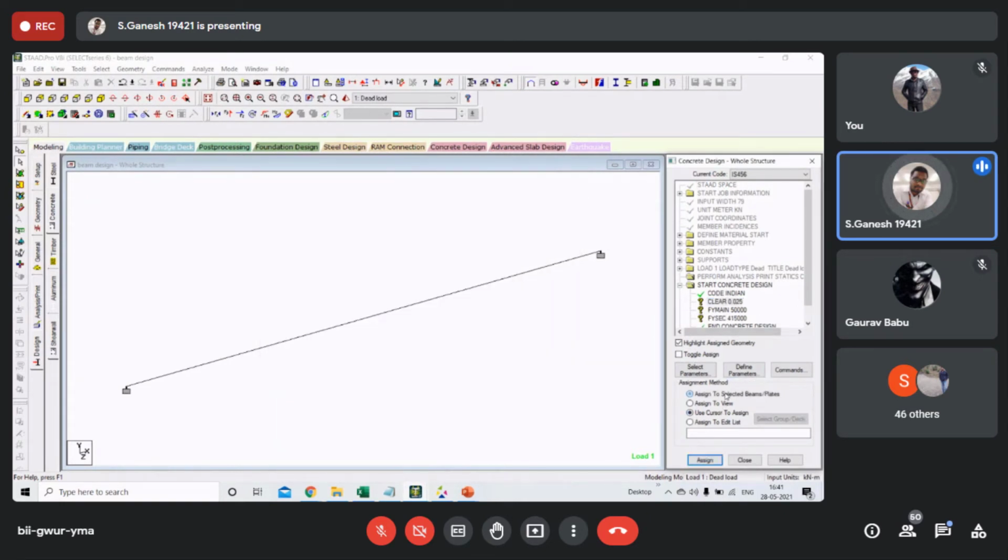So let's go for selected beam, assign, and then assign this also. Do everything slowly to the selected beam. Don't give assign to view. What happens when you assign to view is, when you have a complicated model or some columns, by default you'll give assign to view for all the structures. So you go for a mistake.